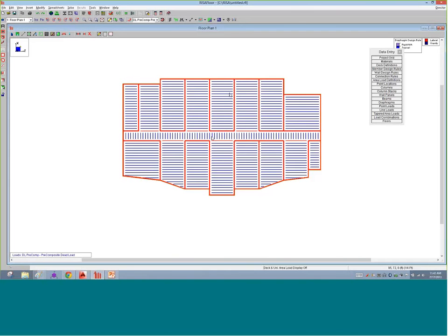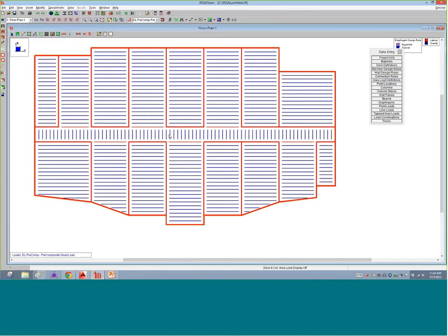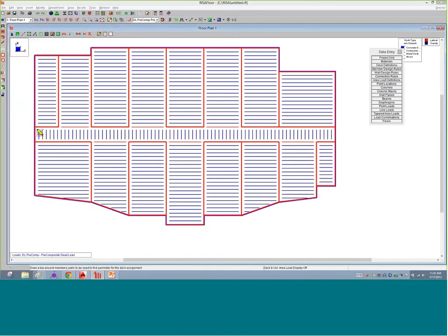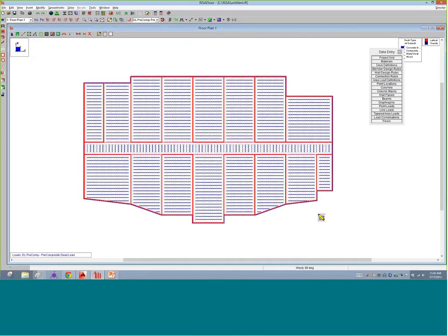But for just that one area where I want to override the default, I tell the program here that I would like to override your default. I'm going to go to the plan horizontal, and I'm going to tell the program to go wood, and I can select that there, and I can just tell the program, hey, go span that horizontally. I can display this with the default behind it, so I see that vertically on the top portion, I choose horizontally in this middle section, and the load is going to be attributed based on that direction.